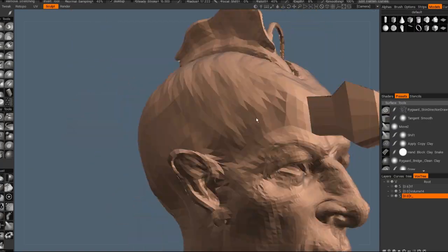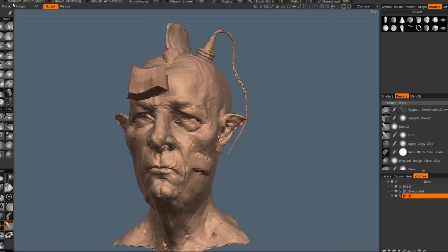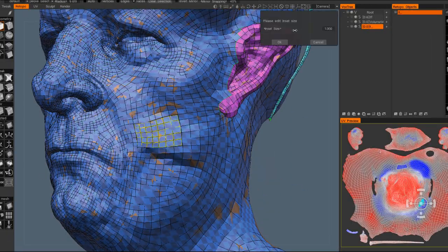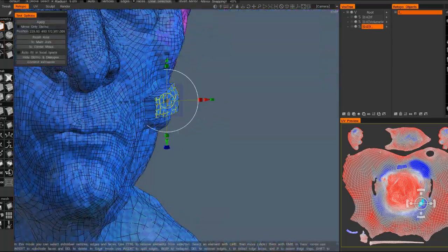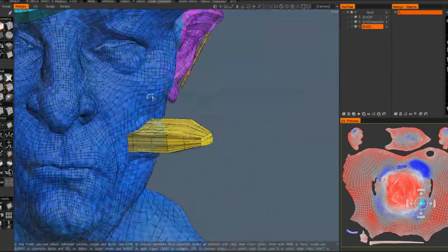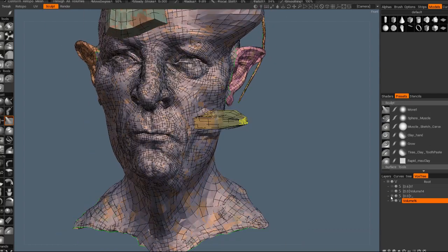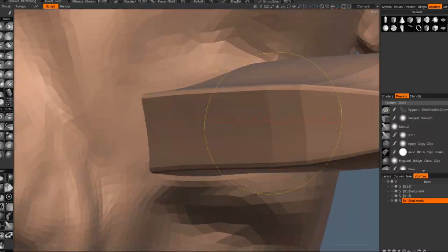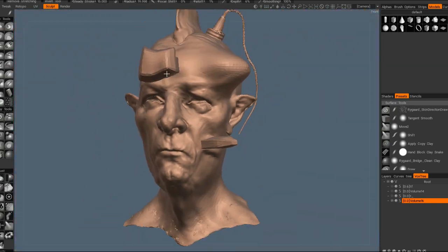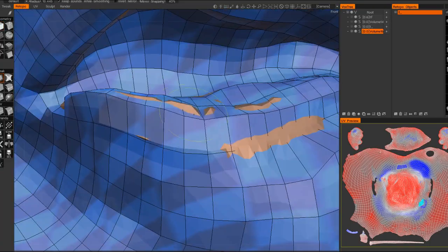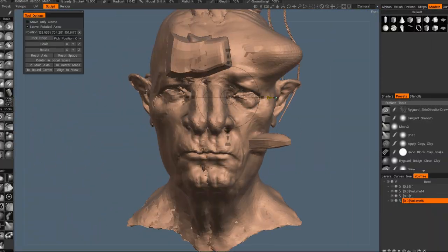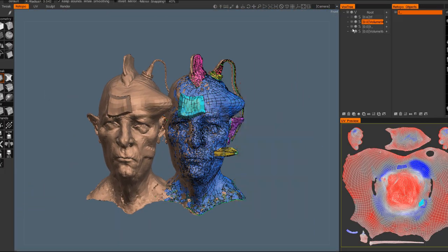If you want to use the standard mesh that is in the Retopo room, you have to send this Retopo room mesh to the sculpt room. And if you have any sculpture working in the previous mesh, you could try using the reproject tool between the two meshes that are in the sculpt room. Every time you want to work with a standard Retopo room mesh, you will have to send it to the sculpt room. There is no direct and real-time interactivity because there is no single mesh in the program.